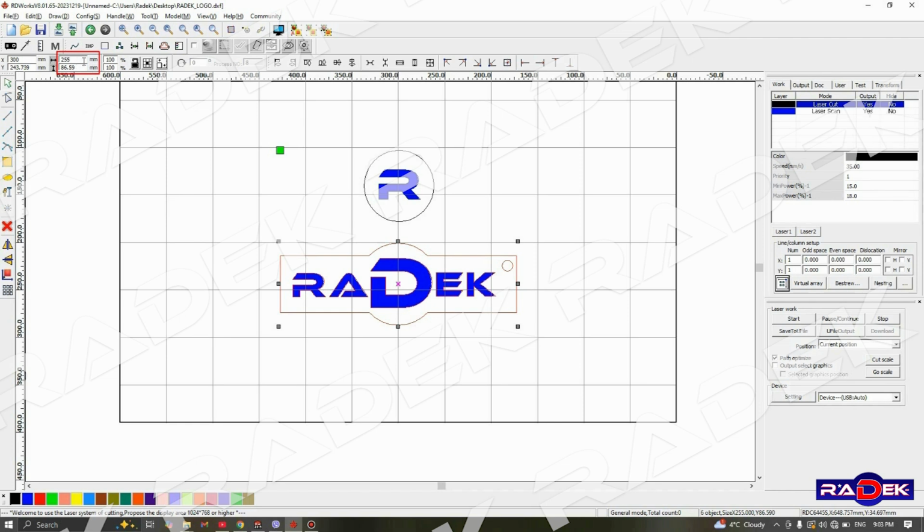The lock icon plays a significant role while changing proportions of our drawing. If it's locked, the vector's height and width are intertwined, and if we change one of them, the other one will change automatically in order to preserve the design's proportions. But if we unlock it and change its width, the height of the drawing will remain unchanged and our design will lose its proportions, and we can see how that looks in reality.